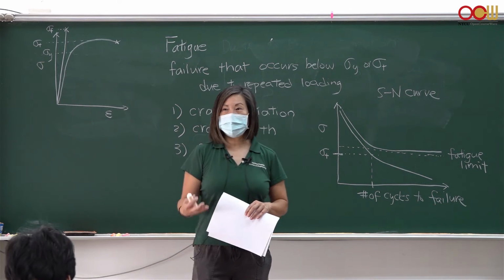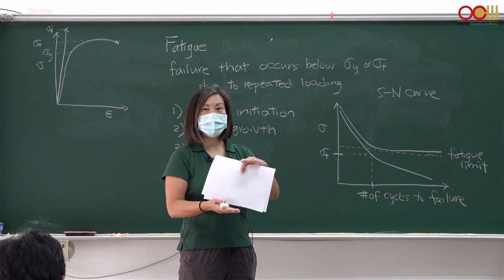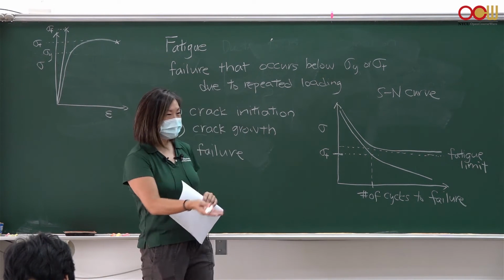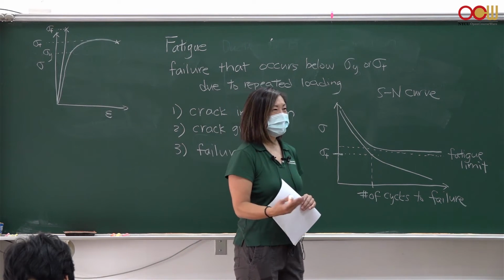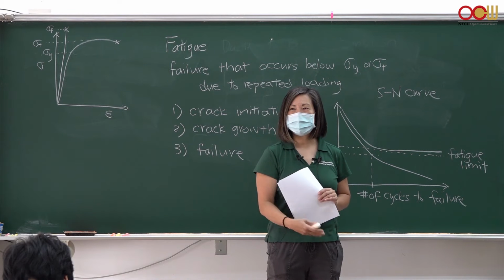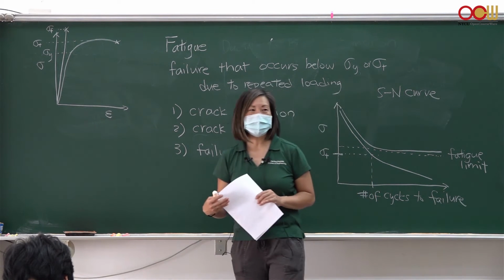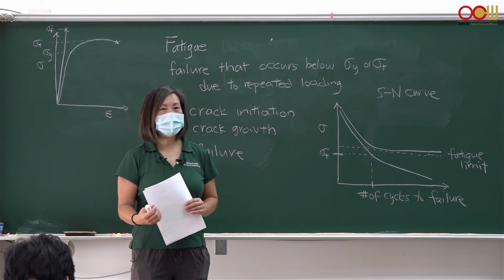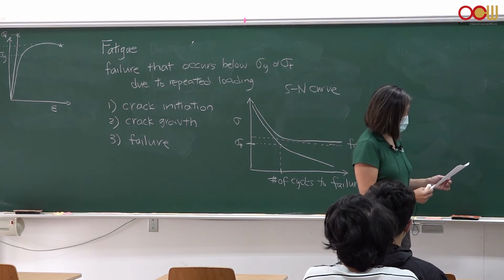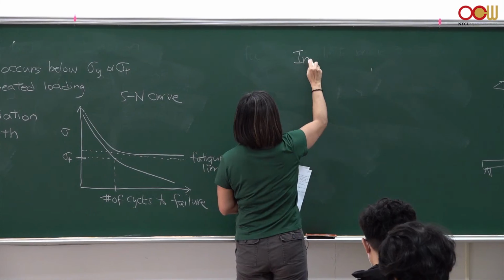Anything that experiences vibrations will undergo fatigue, right? Vibration is just repeated cycling of something. Your chair, the seat that you're sitting on, it's repeated cycling, right? You sit on it, you get up, somebody else comes on it, sits on it, gets up. So that's a repeated cycling of stress. Fatigue is very, very common in material usage, and that's why it needs to be taken into account. One way you can reduce or slow down fatigue is increase surface hardness.